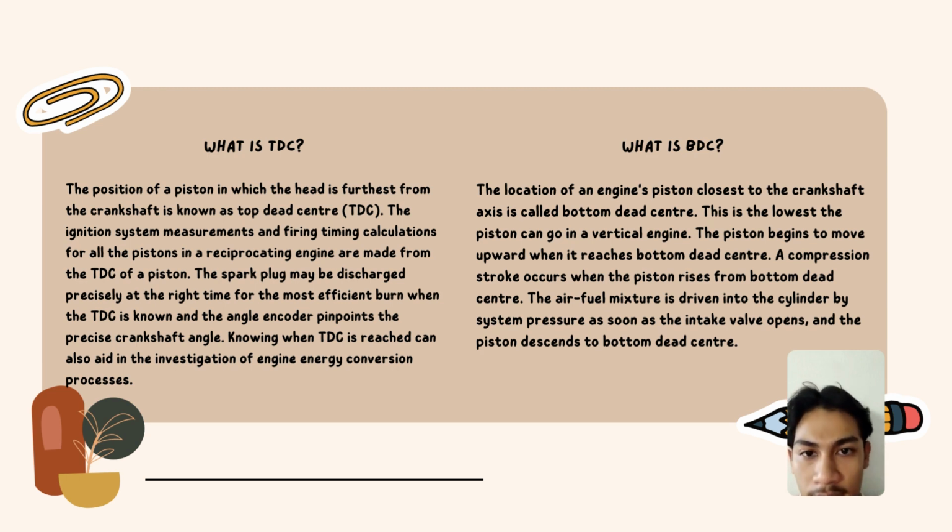The ignition system measurement and firing timing calculation for all the pistons in a reciprocating engine are made from the TDC of a piston. The spark plug may be discharged precisely at the right time for the most efficient burn when the TDC is known and the angle encoder pinpoints the precise crankshaft angle.